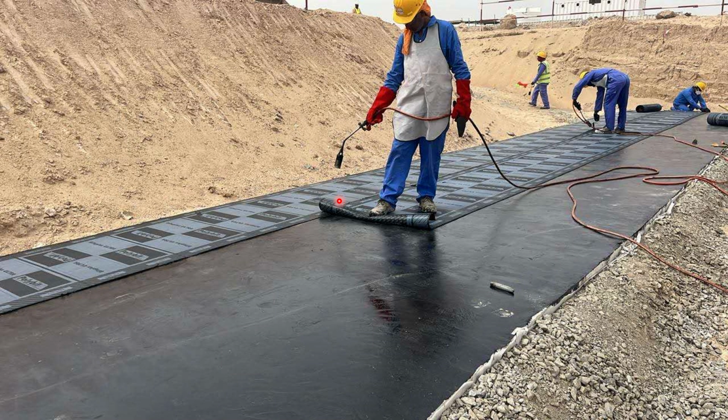When we complete the primer and we are starting application of the membrane, we have to provide the laps, horizontal lap and vertical lap, as I showed in the slide. We need to take care. This is actually the horizontal lap. One membrane we have to lap over another. Some manufacturers also show that this area is to be lapped, usually 10 centimeters, but it depends on the manufacturer. So we have to provide this.